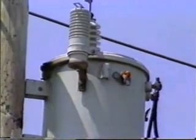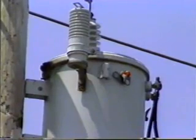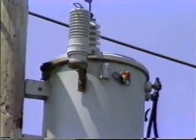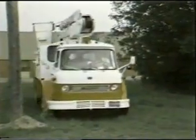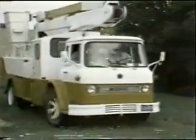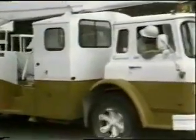Some self-protected transformers have a signal lamp that is automatically turned on when the transformer loading exceeds a certain preset value. One type of design includes a relay which indicates the number of times that overload has occurred since last reset to zero. Troubleshooting crews identify such transformers during periodic checks, and this information can help indicate locations where a larger transformer may be needed.